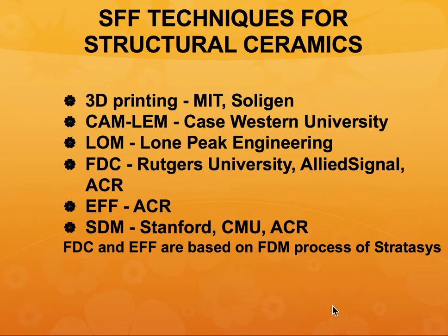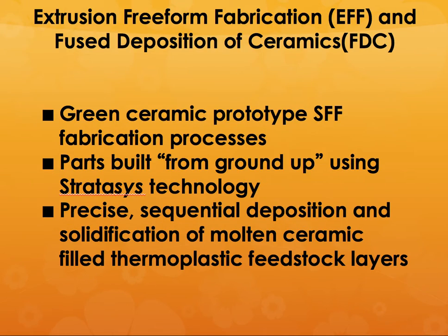To note is that fused deposition of ceramics and extrusion freeform fabrication are both based on the fused deposition modeling process originally developed by Stratasys. Here I'm going to talk more about these two processes, which are both green ceramic additive manufacturing processes for ceramics, built from the ground up using the Stratasys technology. If you recall, you put the material through a heated nozzle, adding thermoplastic binder systems to the ceramic powders. So you have squishy material coming out of the heated nozzle, and you can bond the particles together because of the heat.